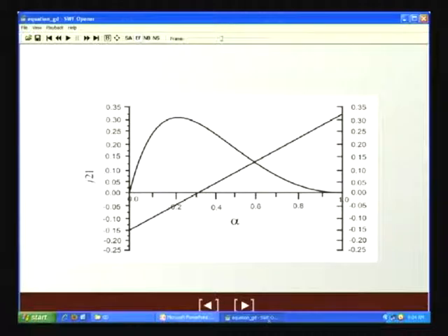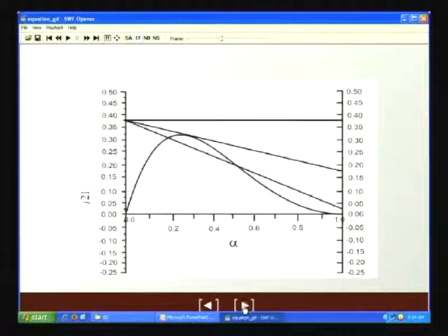Clear? Achha. Then next we found out that for counter current operation, gas up, liquid down, either two solutions are possible, or under one particular situation only one solution is possible. Beyond that, no solution is possible. In other words, counter current operation with gas up, liquid down can occur only under a set of conditions. Beyond the flooding point, it is not possible.